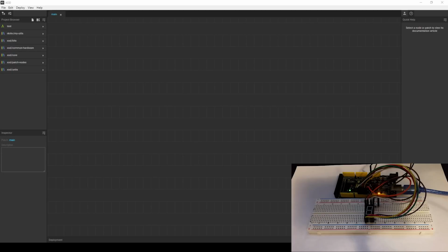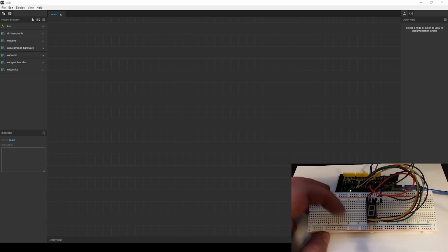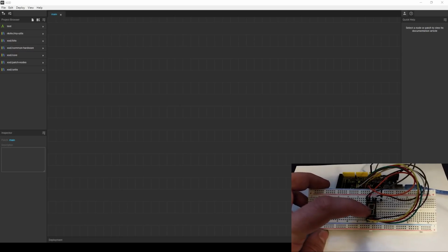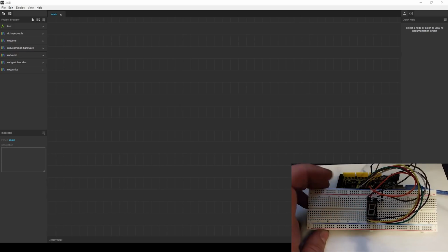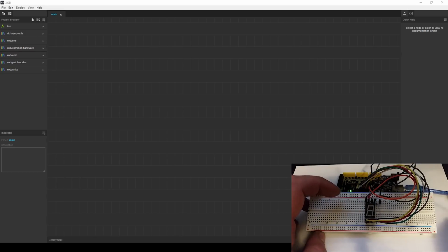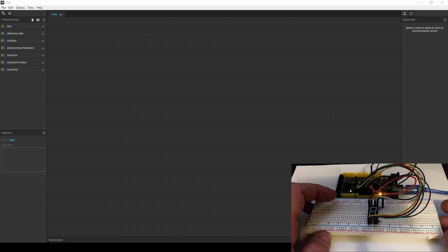Hey everyone, so today in our tutorial for XOD, we are going to be covering how to make nodes from other nodes. And what we're going to be using to do that with is an 8-segment display. As you see down here, it's just a set of 8 LEDs. 7 of them create the number, and then you have an 8th that is the decimal point down in the bottom right. Now, the way that I have this wired up, it is rather easy.